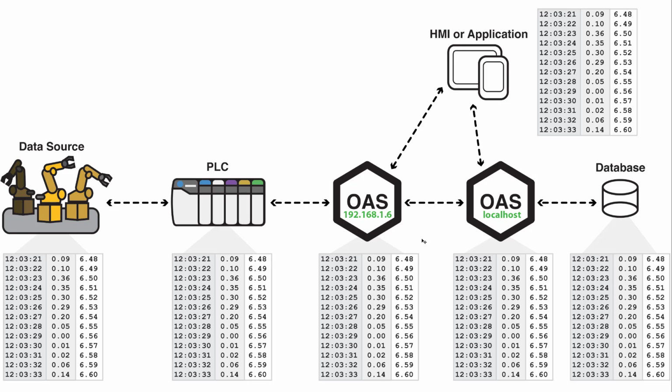And in your scenario, you may not need data at this rate. You might be logging levels or temperatures at a much slower rate. But it's important to know that the accuracy is there for your data models. You're going to want a sampling interval that's at least 7 times faster than the time cycle of the process itself in order to build an accurate data model. And so OES provides the highest accuracy for any IoT solution of collecting data from any Industry 4.0 data source and delivering that data to the database.